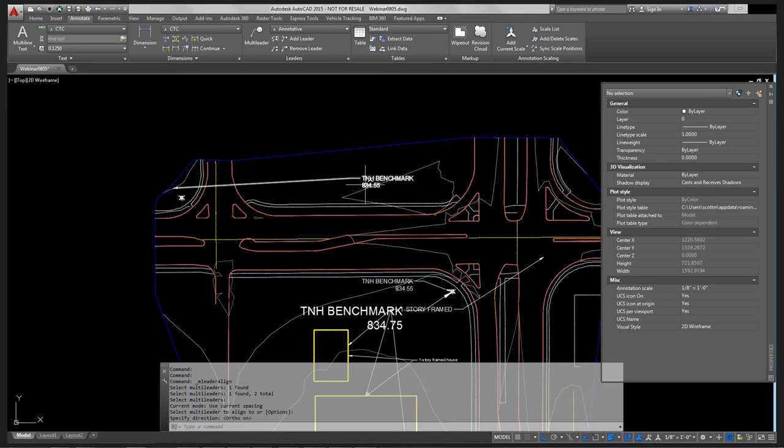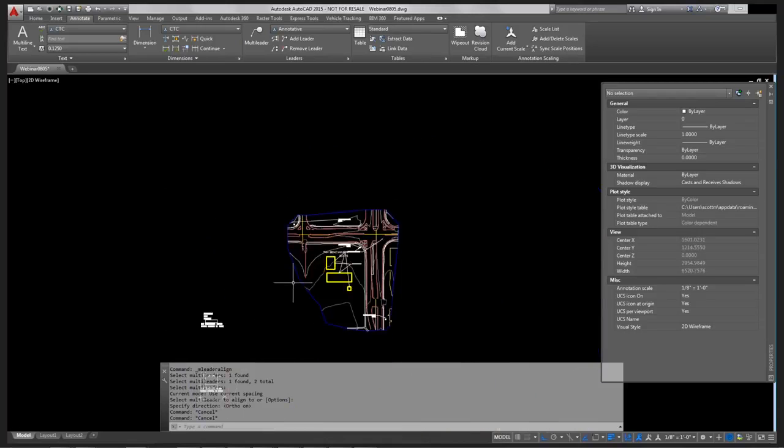It automatically lined up the left side of the note by picking on it. And as you saw when I was picking it, I had the ability to put what angle I want. So I'm not forced to go strictly vertical or horizontal. I could have come off at a 45-degree angle and had my notes stagger upwards like a staircase. So any angle works. Just turn on F8 for ortho mode and it'll kick things out in any angle that you want.